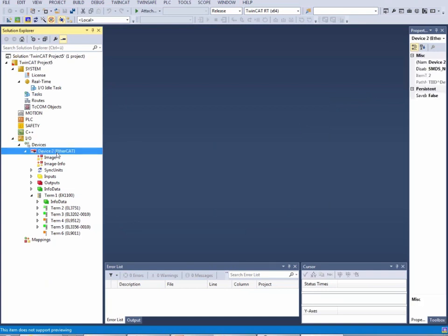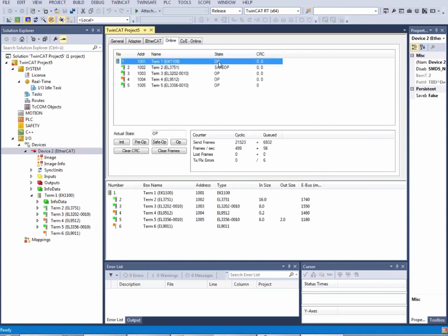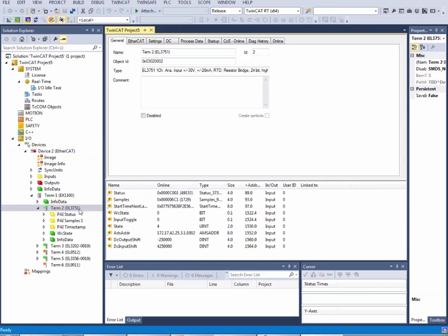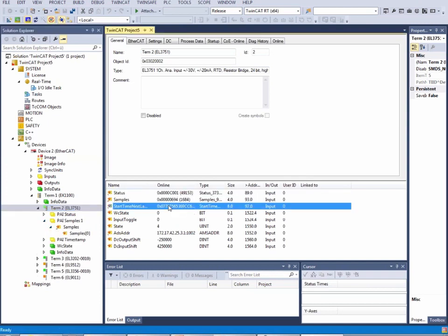But now we will make this EtherCAT presentation, and we will check if this EtherCAT is running, and we see, okay, most slaves are in operation, this is good. And we see that we have 500 frames per second running. This is the idle task. And just for control, we double click on the terminals. You see the channels are opened on this side, and you see the input variables are running, something is living here on this side. So I would say after one minute we have a simple analog system running.